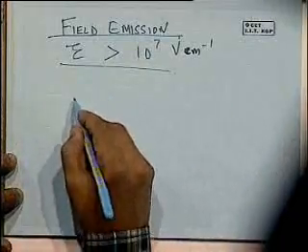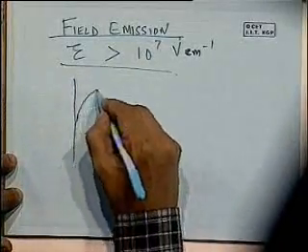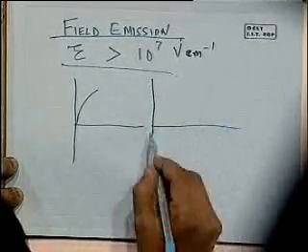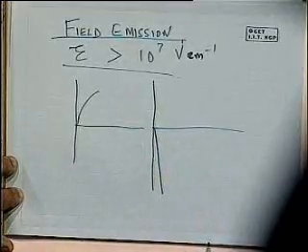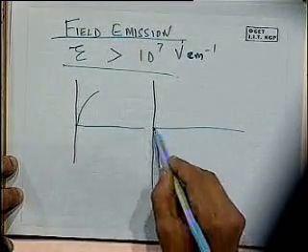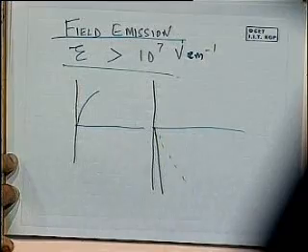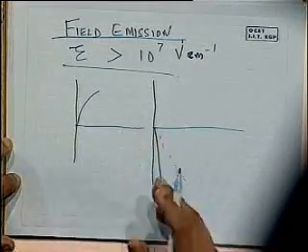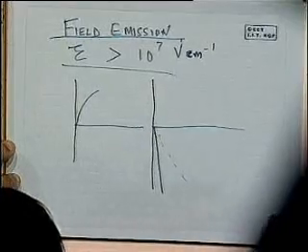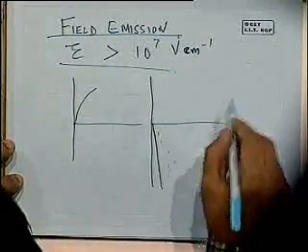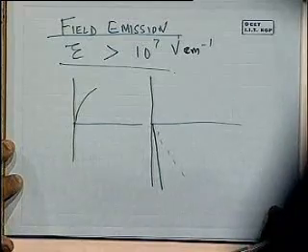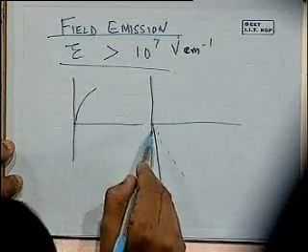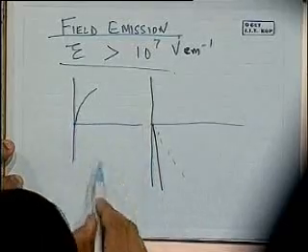And what we are seeing effectively is, as before, we have our image force lowering curve like this, except that now my applied field is very, very steep. Earlier you may think of it as a more gradual voltage drop, so the field is less. Here the field is high, and what I do is create effectively the sum of these two, a barrier that's very, very narrow. This goes up and then immediately this attractive force is there, so it sort of shoots down.